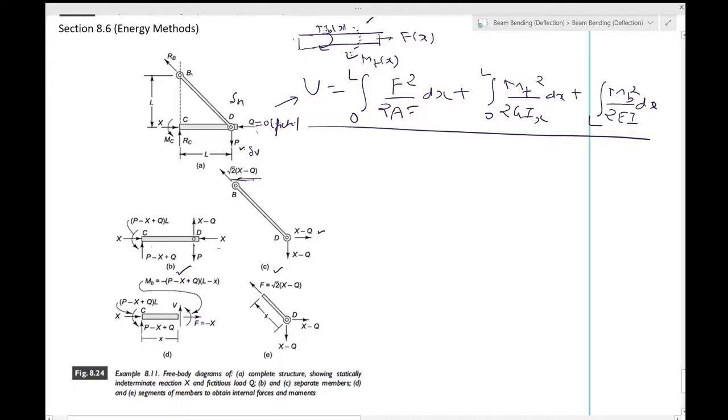Now you want to find the internal force and moments along the section X in CD. So you take this X from over here, from 0. Over here you write the shear force, you write the bending moment. Then you will have the axial force. So these are the three things which you should have over there. And the internal force acting on BD can also be indicated in this form. So you take a distance x from this place, and then you would have axial force only. You are not taking the bending moment over here, and you are not taking the shear force over there.